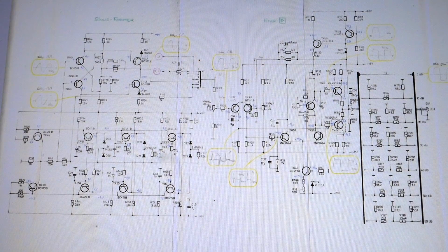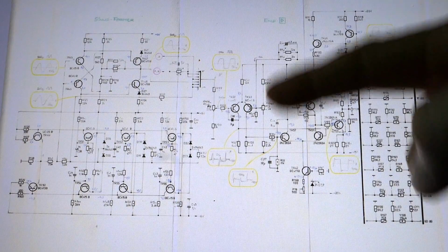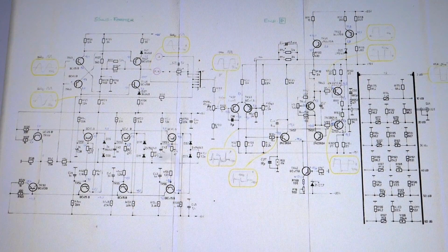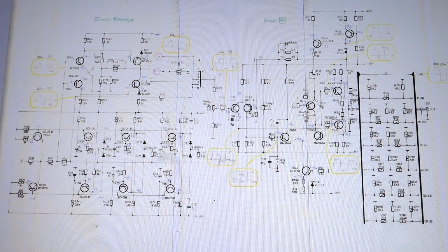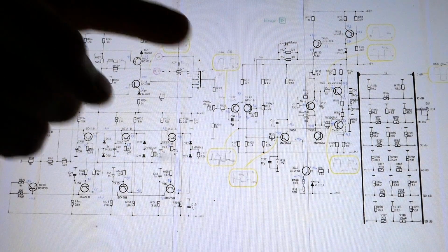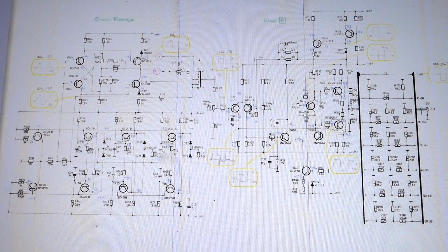But based on the behavior, we can rule out the amplifier and this attenuator. This is working well. If there was a problem, it would be distorting the waveform, not just in some positions of the fine frequency potentiometer. And we can also rule out the problem is in this sine wave shaper, because the problem appears in other waveforms too. And of course it looks crazy to use 12 transistors to make a sine wave, but a simple circuit could produce just a narrow range of sine wave frequencies.